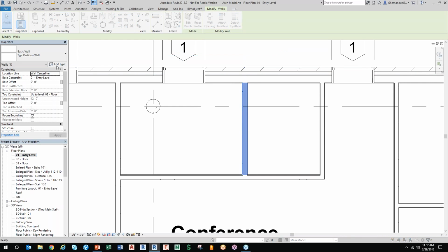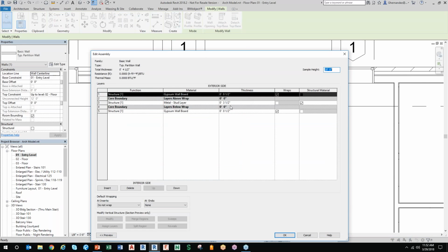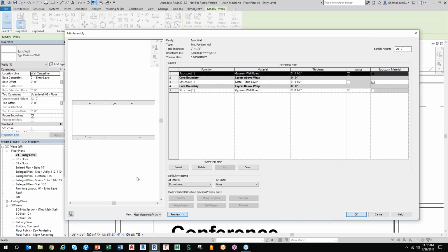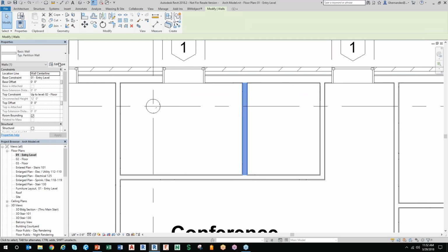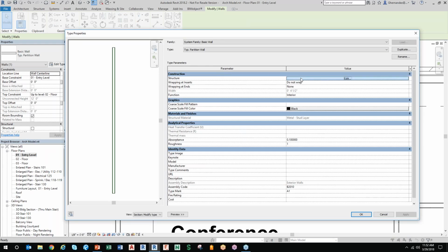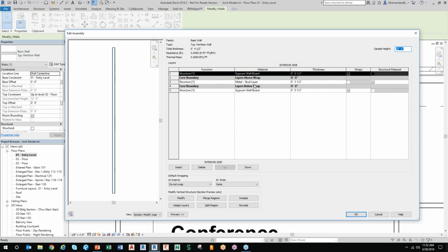When I pick on this basic wall that I'm drawing, if I go into its structure, this is the kind of stuff that really got me when I was learning in the industry. Oh, I'm sorry, I shouldn't have hit escape there, that's my fault. I didn't know that gypsum board was 3/4 inch or 5/8 inch. I didn't know the nominal dimension of masonry. I didn't know the proper dimension of a metal stud or wood stud, right?